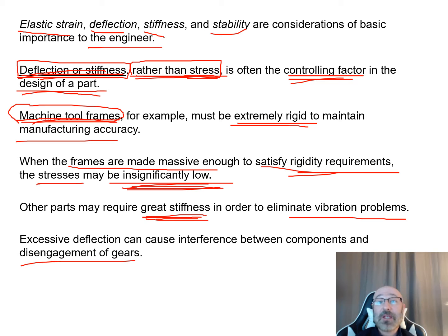The teeth start slipping within the system. So that's where this deflection really becomes the driving, controlling factor more so than the stress. Yes, we're concerned with the stress of the individual gears and all the parts and materials, but if the deflection is so great that it doesn't function as a system anymore, then it doesn't even matter where the stress is at that point because the whole system has already failed. We need to redesign it.